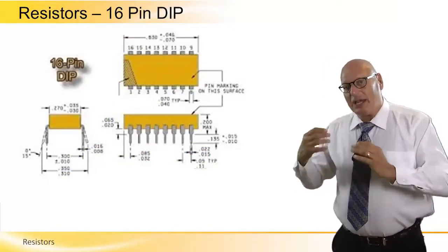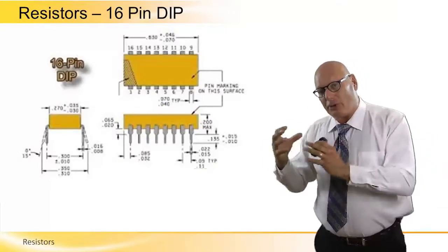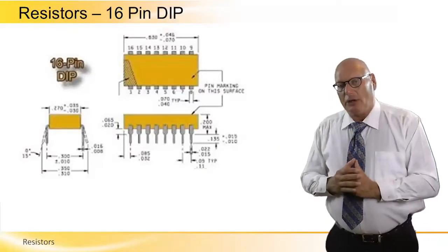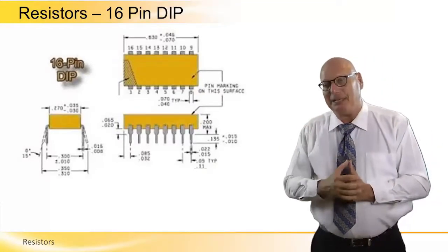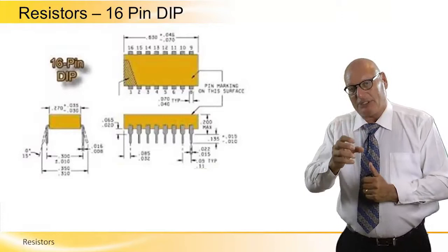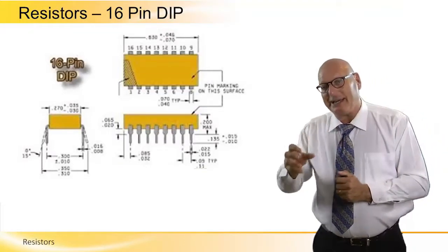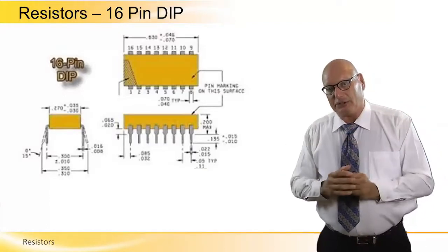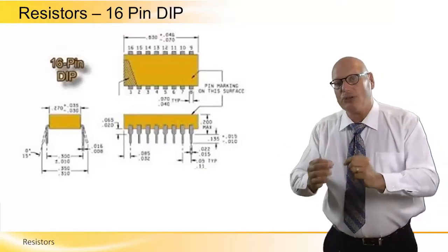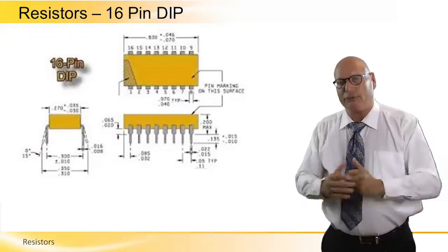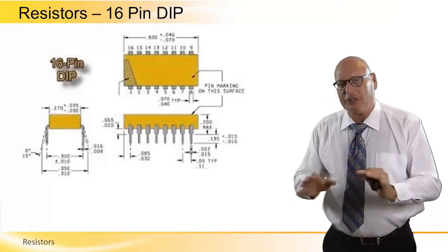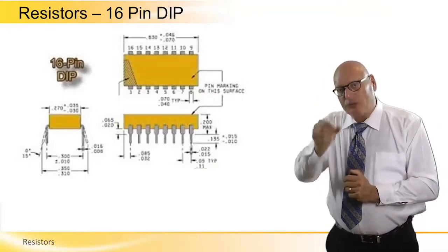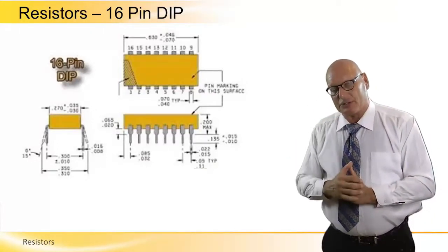Just as we had the concept of arrays of resistors in one package, we have what we call a 16-pin DIP. And DIP stands for dual inline package. This is in a configuration of an integrated circuit, same measurement, same material externally, same type of legs, distances, everything is the same. It's just that inside it, we have a matrix, an array of resistors.